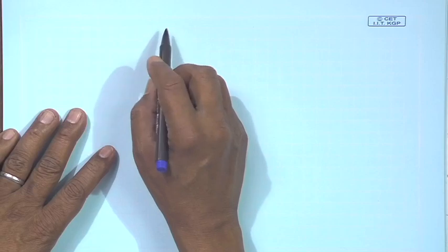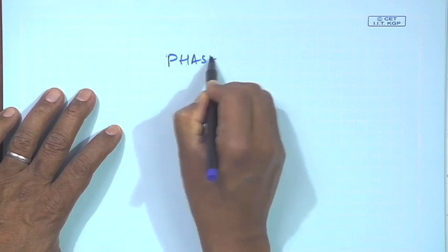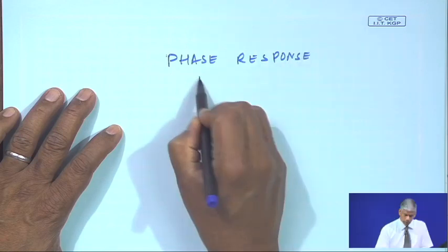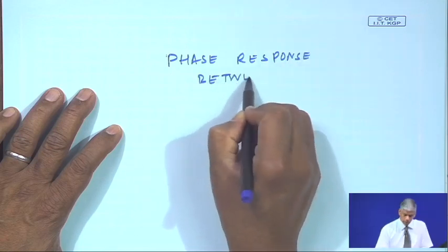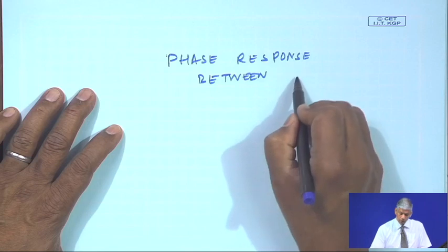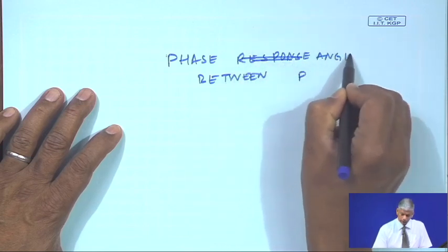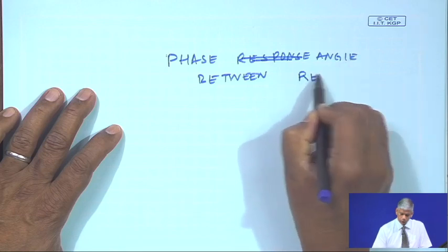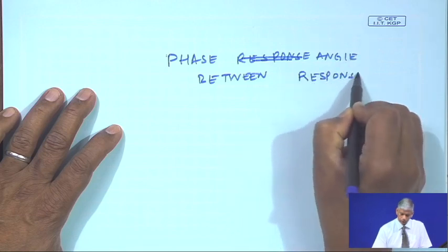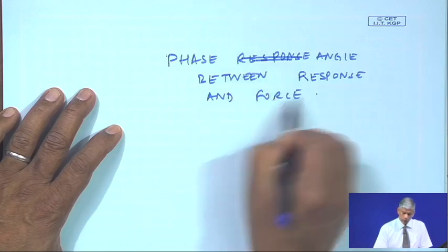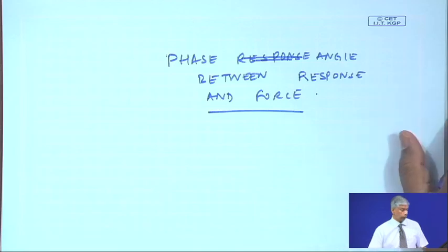Okay. In many systems we need to find out the natural frequency. So, by looking at the phase response, or phase angle, between response and force, we can find out the natural frequency.